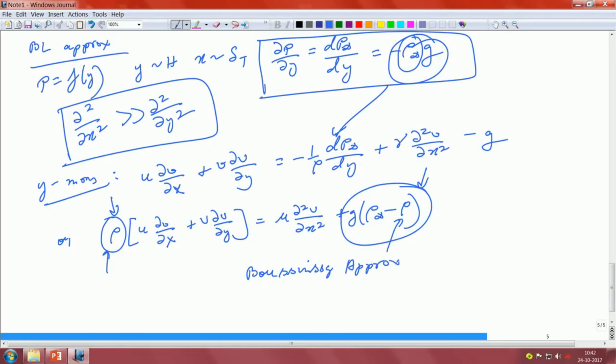So, what does Boussinesq's approximation entail? We will come to that in a little bit. Okay, the spirit of the Boussinesq's approximation is that the density on the left hand side, that means associated with the convective terms, let us take that to be the same density as the reservoir fluid. Let us take that to be constant, okay, point number 1.